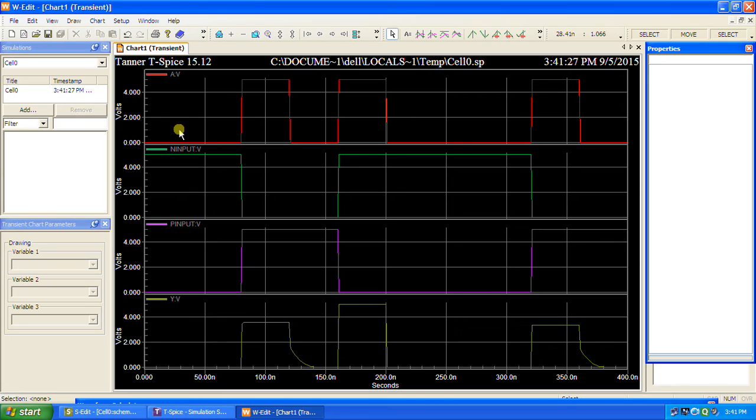Now here it is clear, right? So here initially NMOS inputs are 1, PMOS inputs are 0. Whatever input you get here, A is my input, the same output is going to get repeated. But as soon as these control signals get changed, the NMOSes and PMOSes of the transmission gates are off and the output gets corrupted.